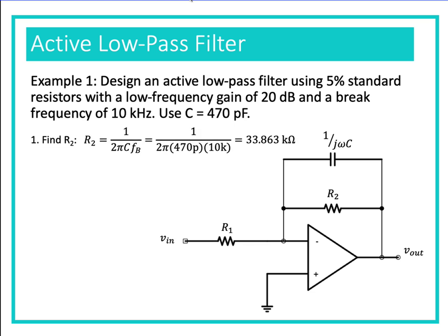So we're just going to switch the break frequency and R2 in that equation, and when we calculate out the value, we get 33.863 kiloohms. It's not a standard value, but we'll deal with that later. We want to keep that original value for right now.